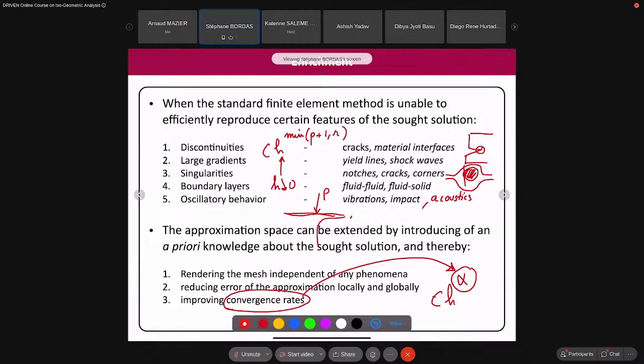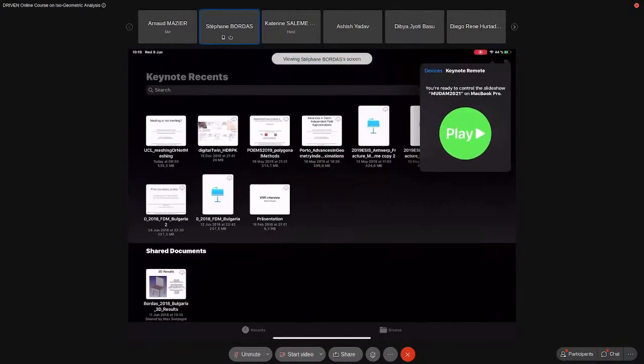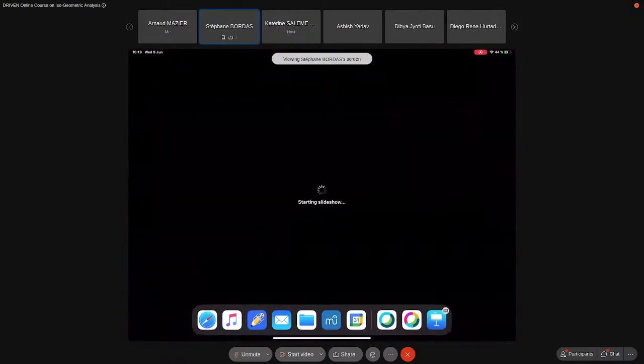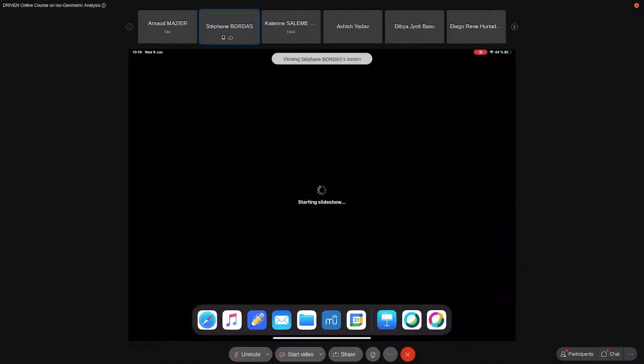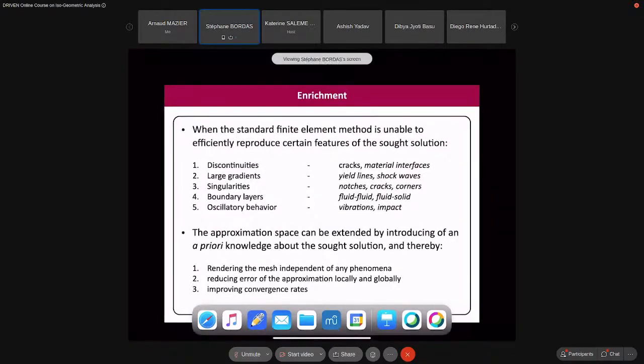It's basically log R, the log of R being the distance to the point load. So the exact solution looks like something like log R, which is naturally infinite when R goes to 0. If you try to model that using finite elements, you will have a case where this R is very low, because the R is the regularity of the solution, right? So if R is low, then your error level will simply be converging very slowly. Okay, so that's the idea.